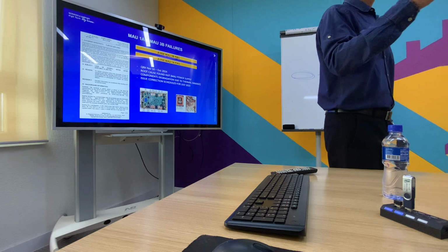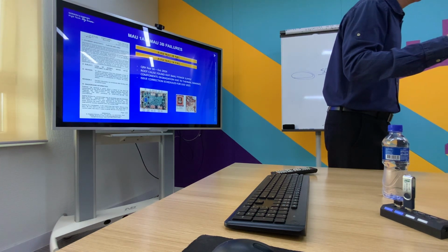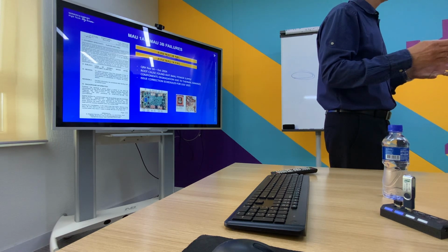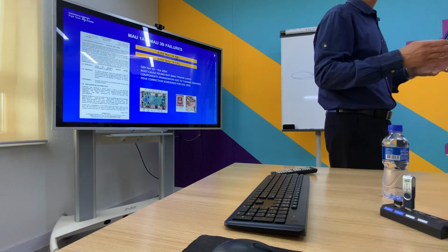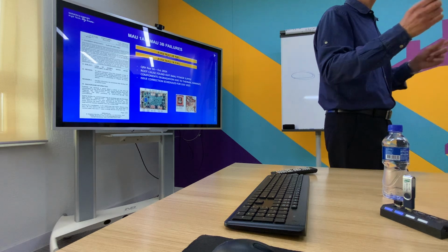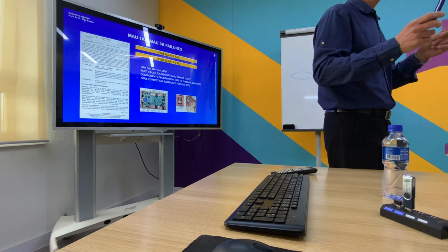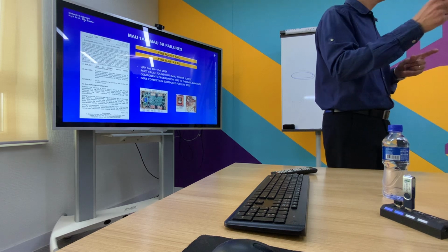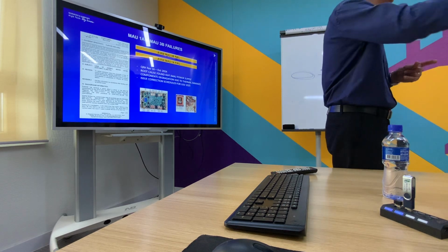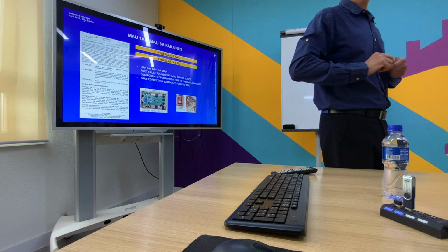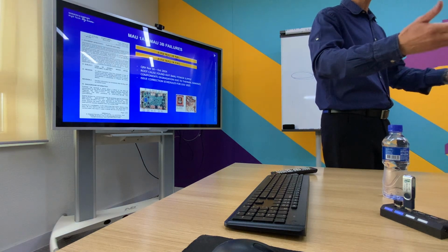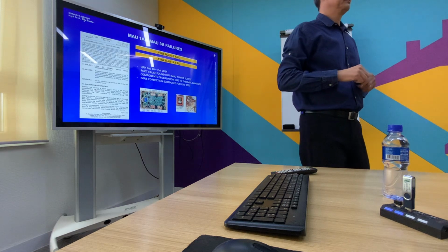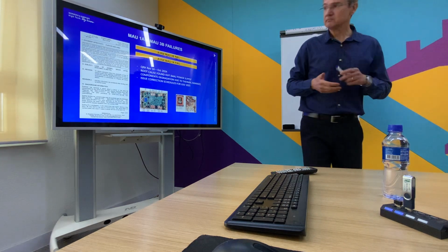Try to re-engage after doing the procedure and you may fly the airplane with the autopilot. It failed just because of the ADS failure and sometimes reversion from the ADS, right? When you lose the ADS1, the ADS3 will power the PFD number 1, and you can lose the autopilot. If you lose the autopilot with this failure, try to re-engage it to make your life easier.